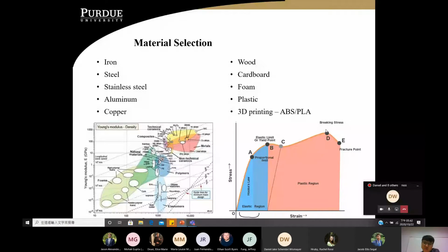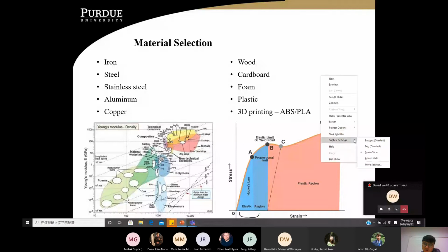So we have the fracture point over here and then breaking stress. We'll talk about that a little later. The other thing I want to talk about is this region here, which I'm coloring in blue, and the plastic region I mentioned. If we do an integration, the entire area over here is basically the material's energy absorption. Some design teams consider impact, where you quickly hit something and it fractures and breaks. So that's the energy absorption we look into.